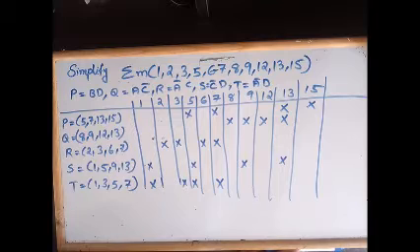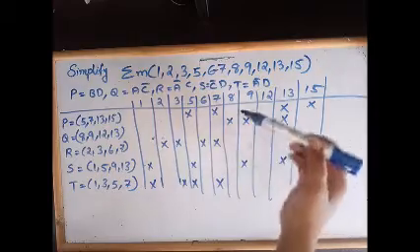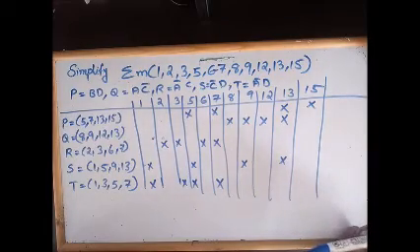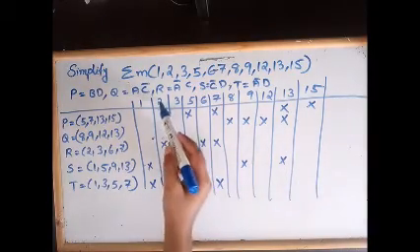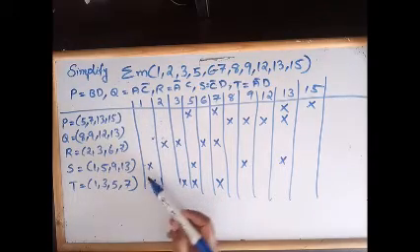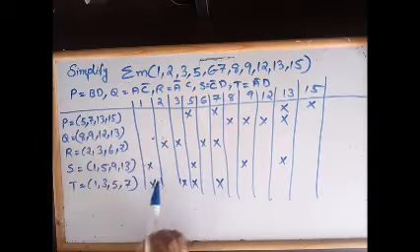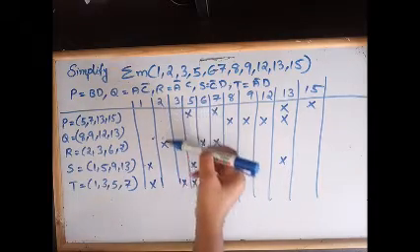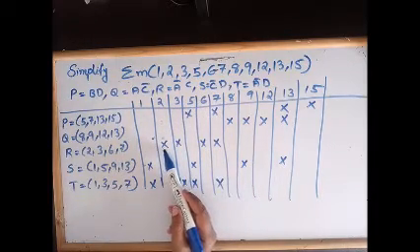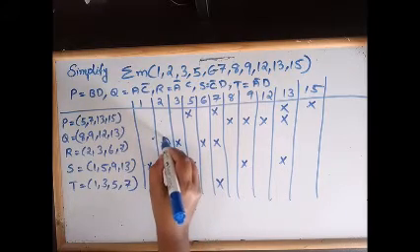Then the next step: identify the min terms with a single cross mark. When you consider the first min term, there are 2 crosses in the column, so no need to consider it. The second min term has only a single cross, so we need to consider this.